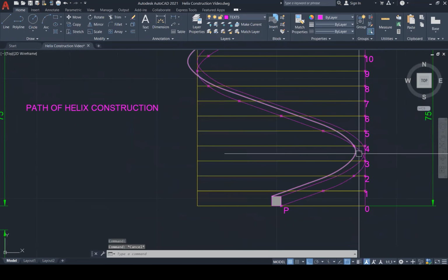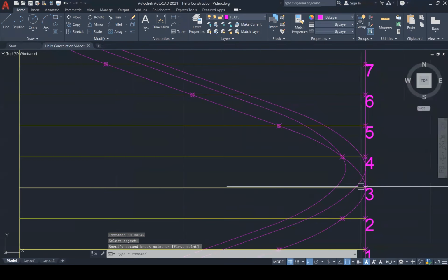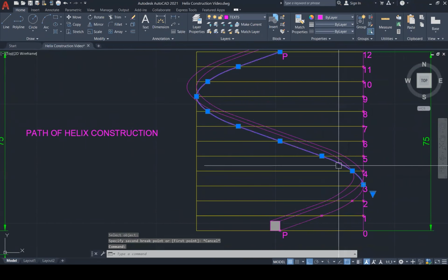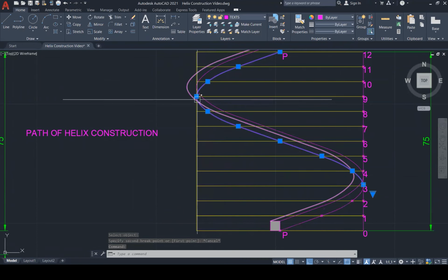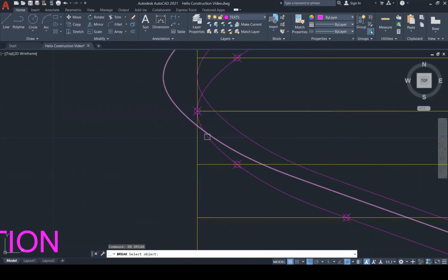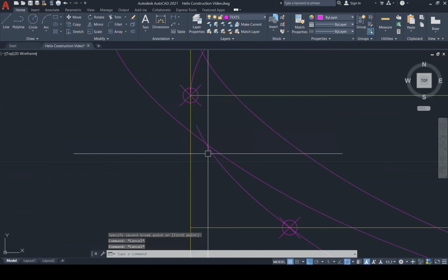All right. So I'm going to break this line right there. So I will know that immediately at this moment goes into a hidden line. And it goes all the way hidden until it comes right back to here. So just going to put a break there again on it right there. So this is an individual line now.